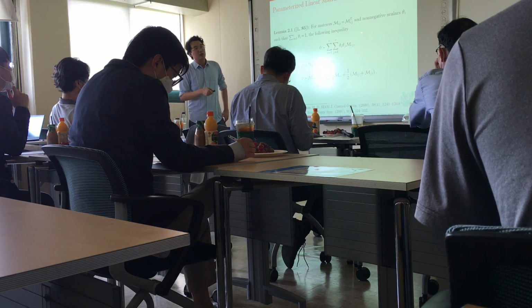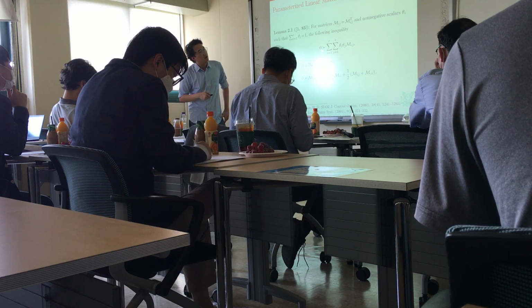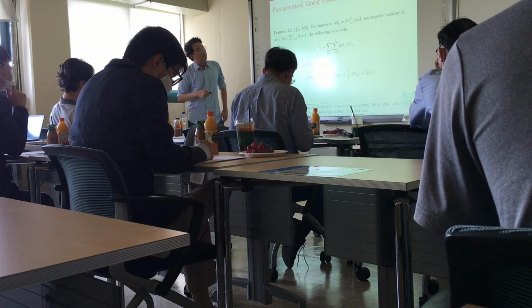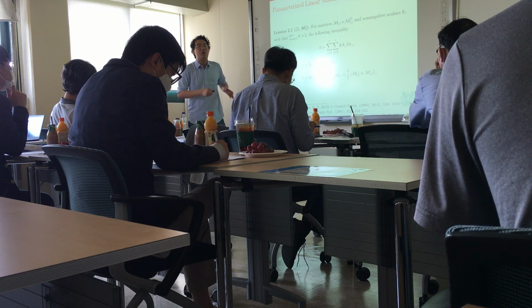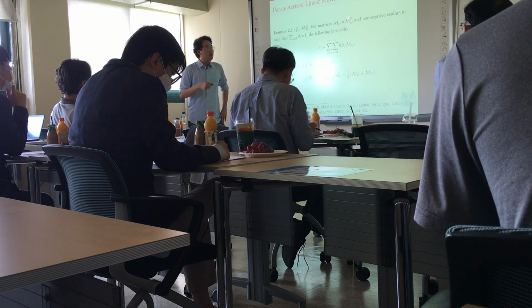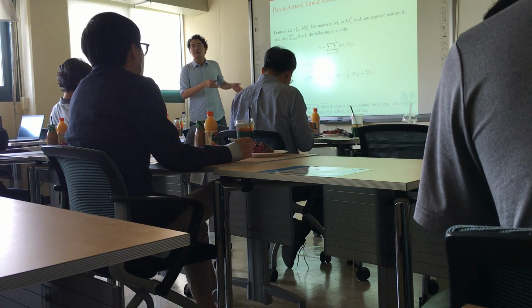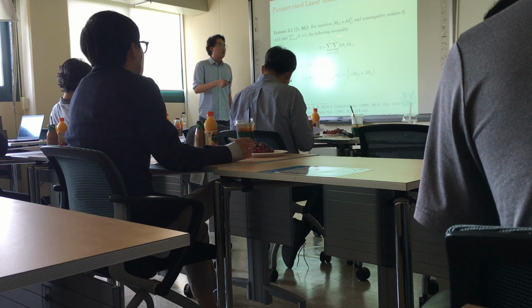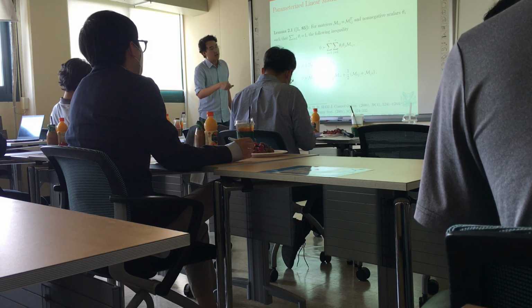The most beautiful thing in this lemma is that we can convert this double convex combination into the linear matrix inequality without any additional slack variable. You can see there is no relaxation, there is no additional slack variable to convert this PLMI into the LMI.